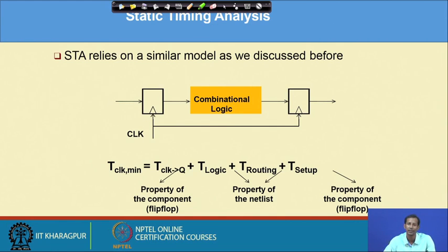there are 4 NAND gates, right. So, the clock has to pass through 2 levels of these NAND gates. That means the flip flop itself has some delay for propagating the clock to the output. Okay. So, that delay is mentioned over here. This is T clock to Q.